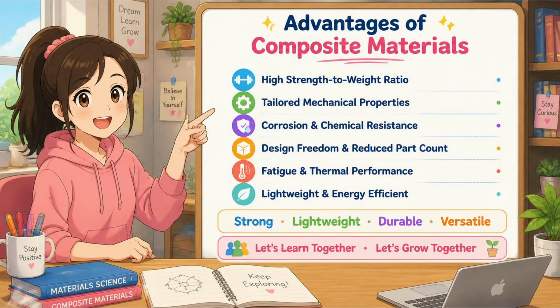The next one is design freedom and reduced part count. Composites can be manufactured into complex shapes. Several components can even be integrated into a single composite component, and this can reduce parts, joints, fasteners, and assembly operations. The next one is good fatigue performance. Many composites perform well under repeated or cyclic loading, and this makes them useful for structures that experience repeated stresses.